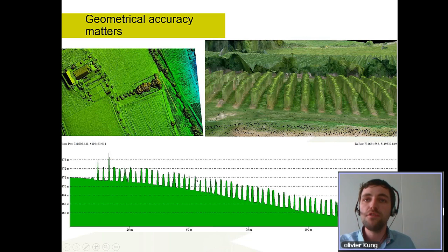If we wouldn't model the nice 3D position with the DSM, we would mistake the pixel for another value, and they will not be nicely aligned, and you will start making mistakes when computing your NDVI. So having a very precise 3D model behind, which is also computed automatically by Pix4D Mapper, is extremely important when doing accurate plant-level NDVI.